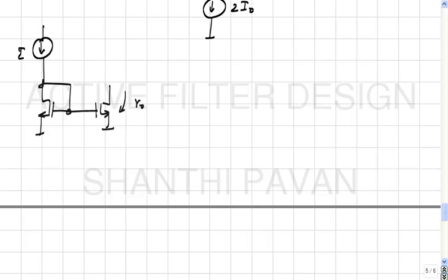Ideally, if this was a perfect current source, then regardless of the voltage, I mean infinite output impedance. Yes, what does that mean in English? Regardless of the voltage across the current source, the current it sinks will be absolutely the same. That's what it means, right? Unfortunately, that's no longer true with a current source with a finite output resistance.